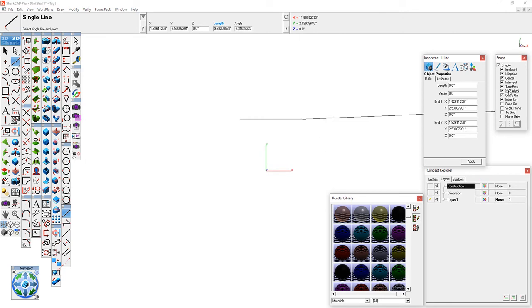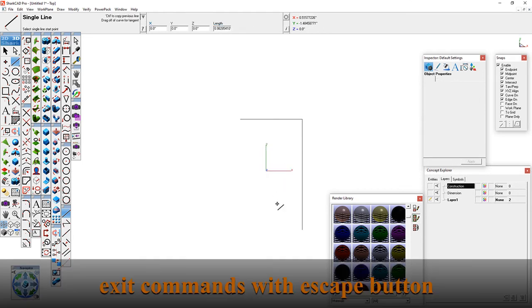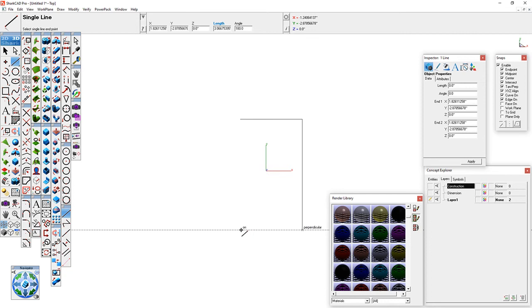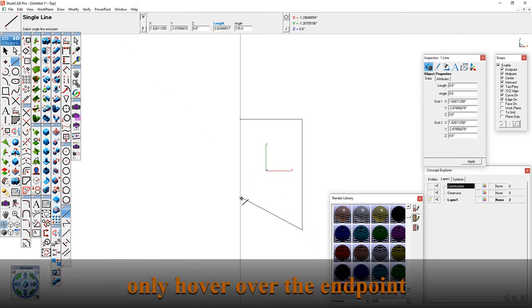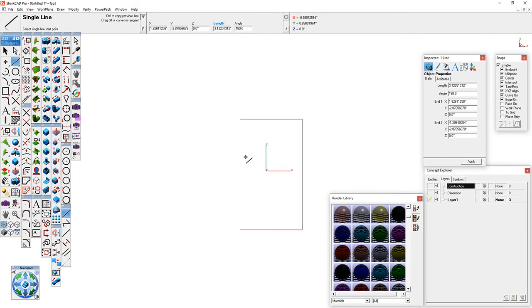That is this align XYZ. If you turn that off, it's doing perpendicular now. I don't know what it gets that from, but it automatically chooses perpendicular. But when you do XYZ, you'll see it'll do perpendicular, but it's here. Let me do one of them here. See, along Y, along X. So we click the end of this and we go over here, and if we pick that endpoint and come back down, it'll line that up, and now we can just connect these two.